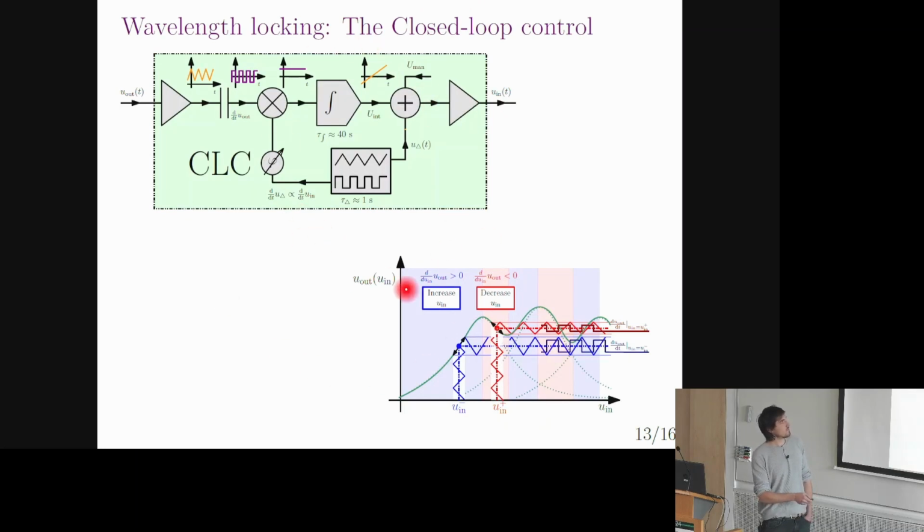So this was the control loop system block schematic that we came up with. The idea was basically to get the signal from the photodiode, to take the derivative of that, to mix it with a reference sawtooth signal, and to use an integrator to basically find the correct value, to align the wavelength such that maximum energy is coupled into the photodiode at the drop port.